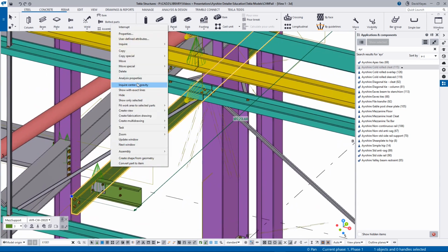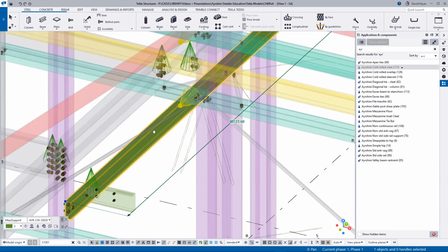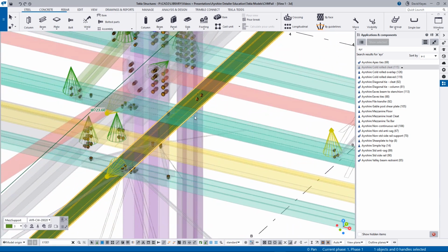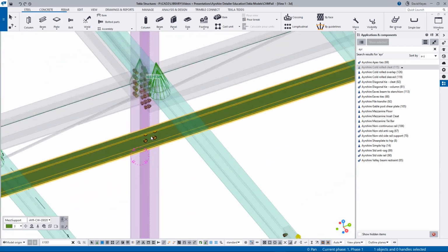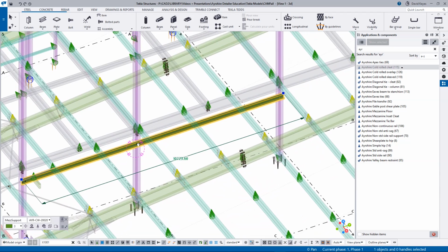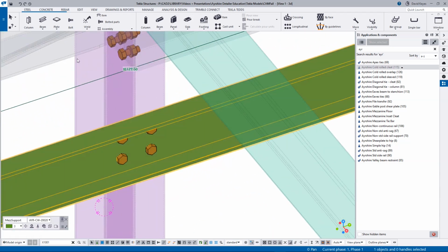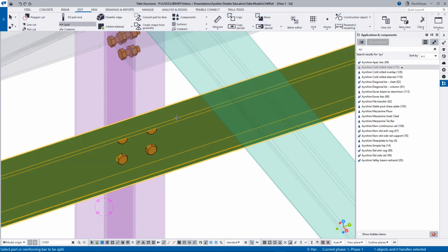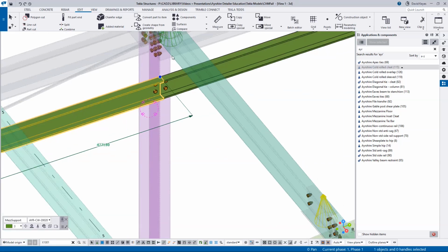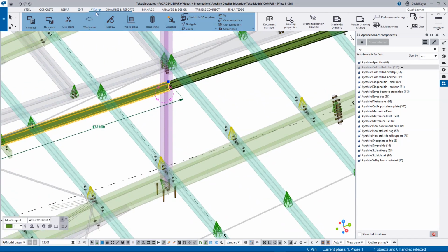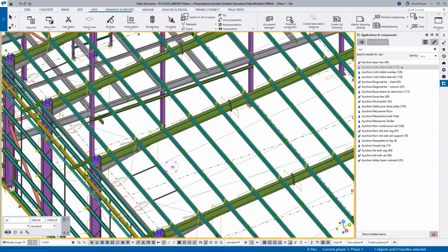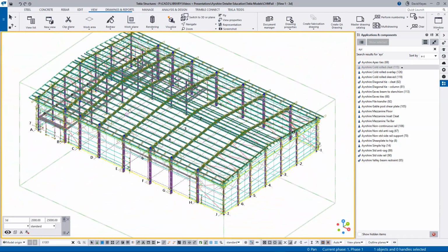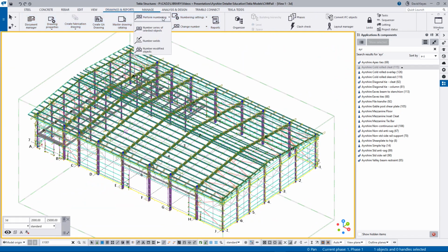Use Show Only Selected to make the part a bit easier to see. The maximum lengths for Ayrshire CW and CJ profiles is 10 meters. The Zs and Zeta profiles are 17 meters, and eaves beams are 16 meters. We can split this beam where it passes a stanchion. Number the model, and rerun the Ayrshire File Transfer 92 macro.